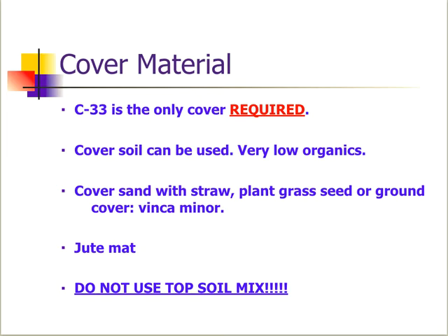What we don't want to do is to put a topsoil mix that you get from the commercial establishments that have a lot of compost, heavy organic material. That material tends to hold water, and it gets a little mushy, and it looks like your system's failed when it hasn't. So we discourage the use of commercial topsoil mixes. Just use mineral soil, and really the best thing is just to leave the top, just the sand itself.